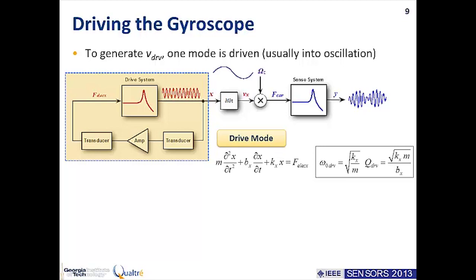And going back to your question, where you would place that amplitude control circuit will be somewhere around this chain. So you monitor either this amplitude or this amplitude, and then you feed it back to this amplifier. So you control the gain of that amplifier to make it constant with respect to our reference. And obviously, where we want to establish this oscillation is at the resonance frequency of that mode.